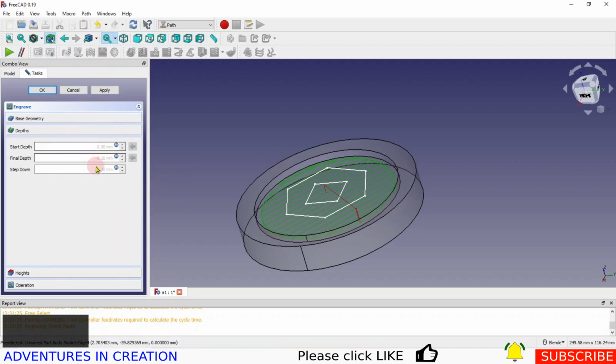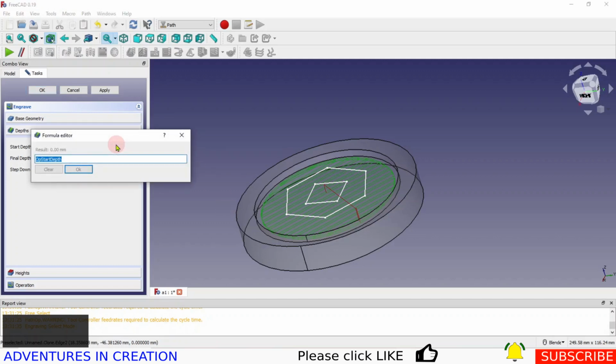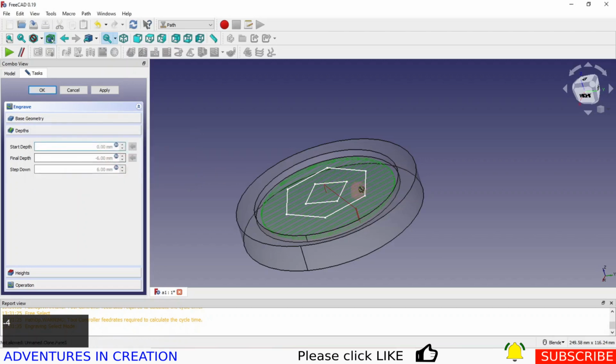And our depths. So our depth here has gone in at 0.1 millimeters. And the start depth has gone in at 0. So what that would do is it would be here, and it would go down 0.1 from there, which would be cutting in midair. So we don't want any of that. So let's open this up. We're going to call this -4. And what that is that surface in there. So it's going to cut into the surface that we just cut out.